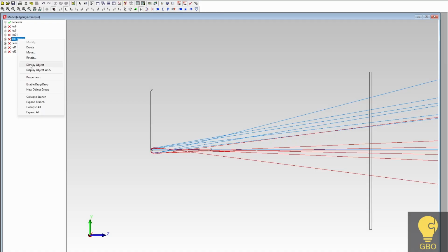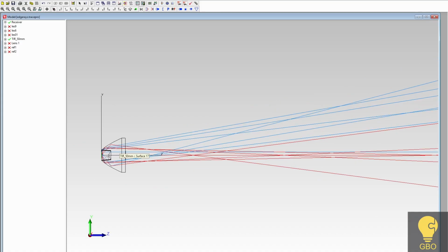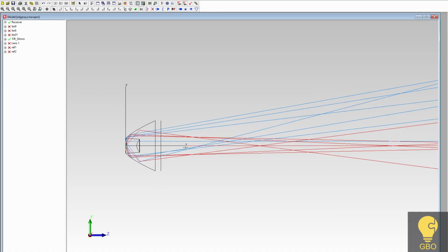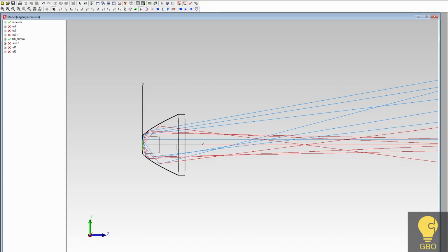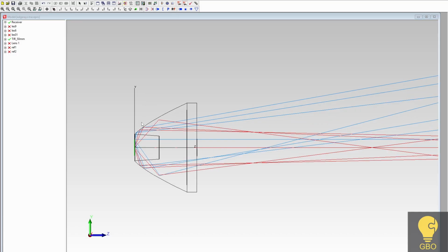Now let's take a more complex case. Not a simple reflector, but a lens that splits the beam. A lens of this kind, a TIR lens, splits the beam between a central zone and the external zone where the TIR happens. How do we define the edge rays in this situation, since the beam is clearly split into several parts?